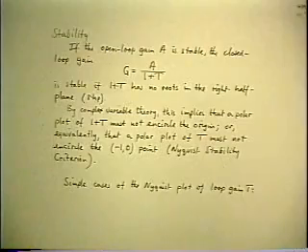That's an instability. So it's easy to see why all of the roots of the denominator have to be 1 plus s and not 1 minus s. So that's basically the stability requirement. Notice there is no requirement on the zeros. You can have right half plane zeros of the form 1 minus s, and the system is still stable. That's why when we talked about right half plane roots, it's okay for zeros, it's not okay for poles. So that's the basic definition of stability.